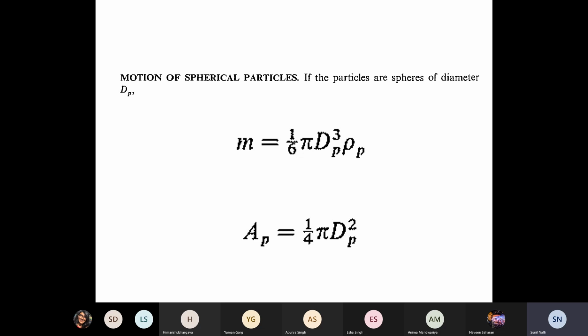Rather than start with a very specialized shape and a very specialized flow regime, we are starting with a very general expression, which is even valid for an accelerating frame. Then we gradually, one by one, limit it. First to du/dt equal to 0. Then we limit it to the geometry. In this case, for a sphere, we get a general expression. Now we are trying to limit it to the very special case of the creeping flow of Re less than 1, which gives the inverse dependence of the CD on the Reynolds number.